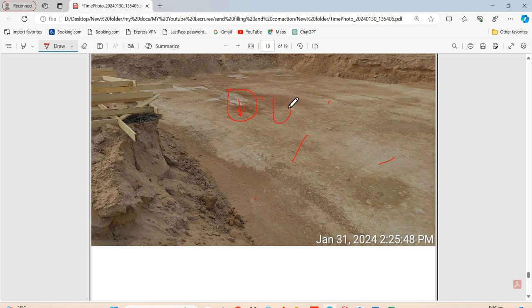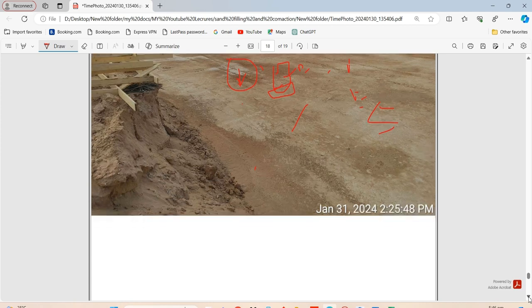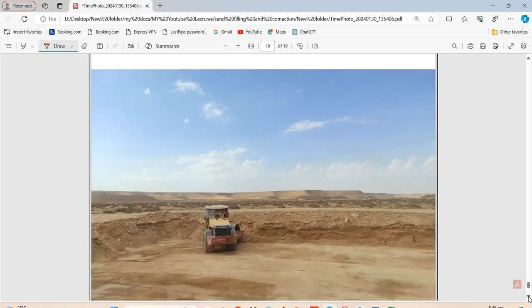When you place that field gauge instrument over here, that value will show that the maximum moisture content value is exceeded. So that test will also fail if you achieve 95% compaction but your moisture is more. So you have to be very careful about sprinkling water. There should be an engineer or foreman placed on the site. Let me show you more pictures.